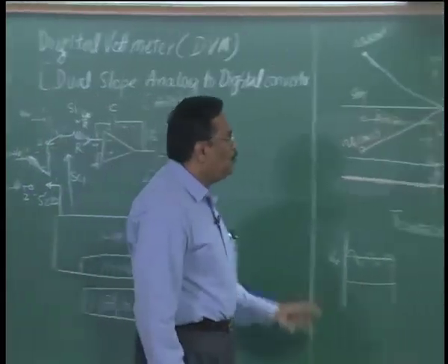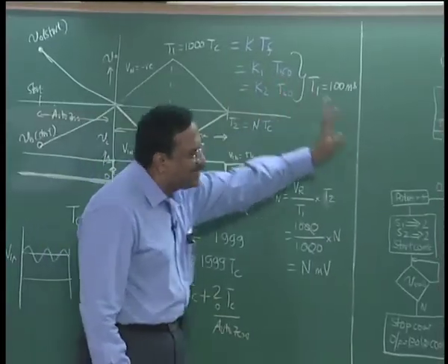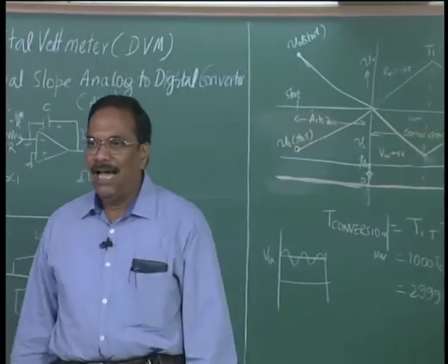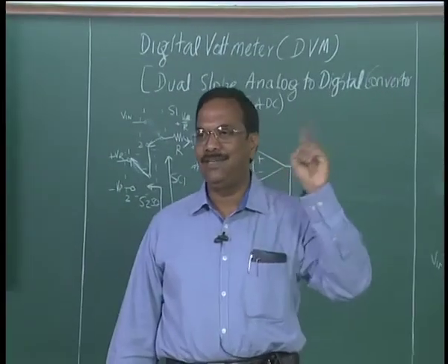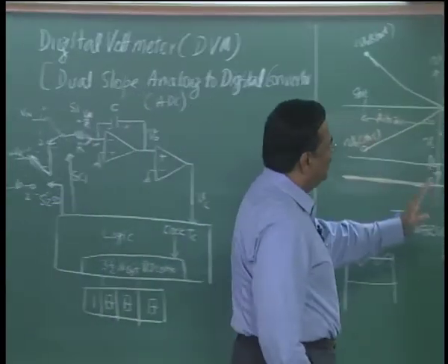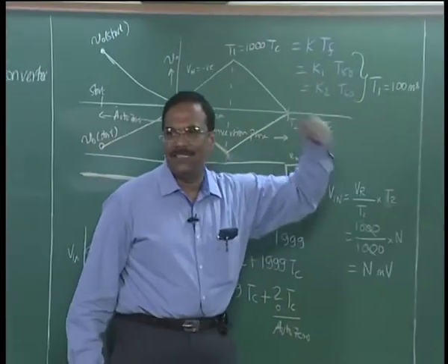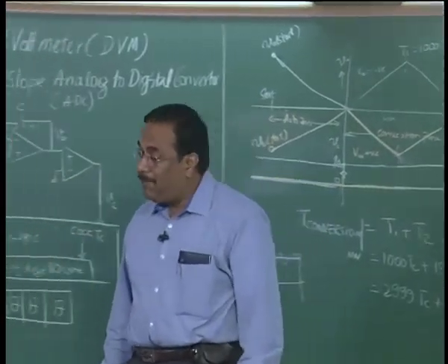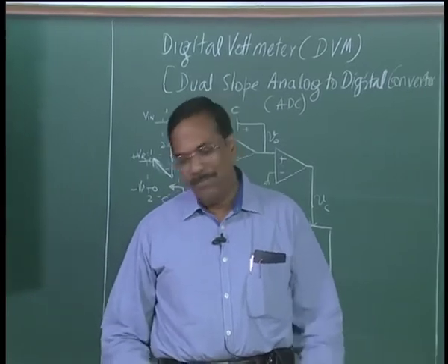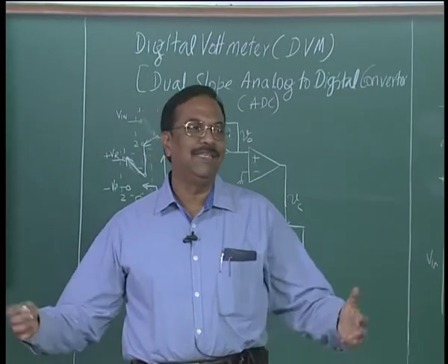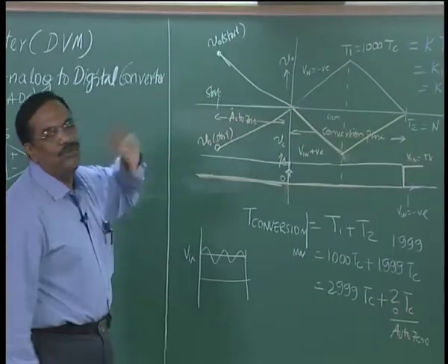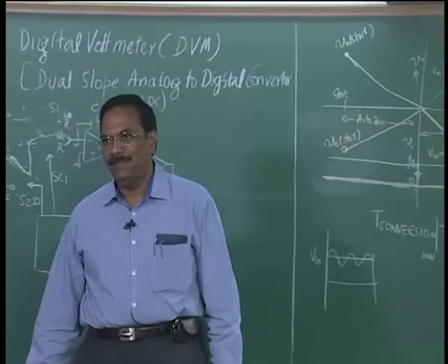If I do one conversion after the next conversion, we call this continuous conversion mode, and I need to do the auto 0 phase only once, at the start. I finish one conversion, start another, and continue to do that. If I want to do start-stop conversion, I start conversion, stop it, maybe wait for some more time and start again some other time. Every time I do the start-stop, I must have an auto 0 phase.